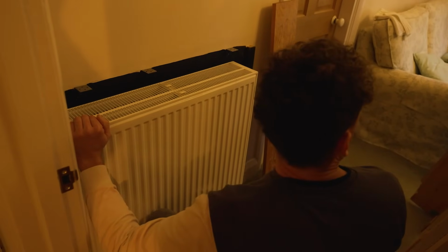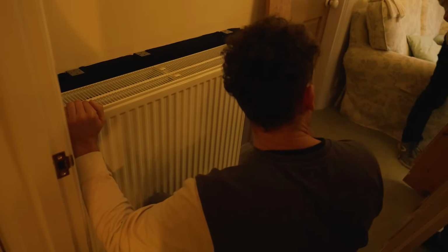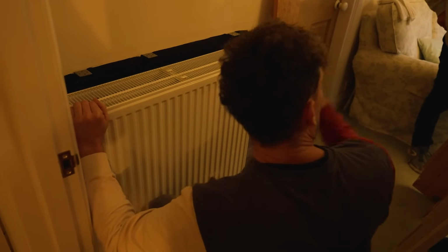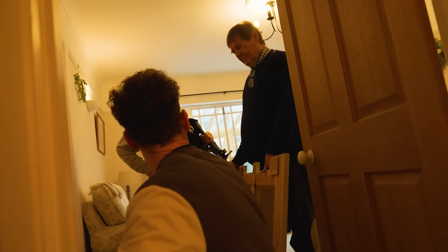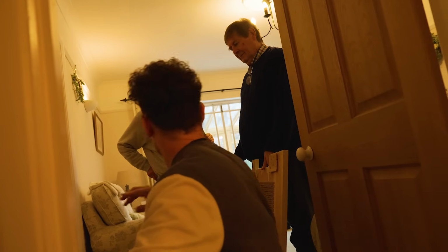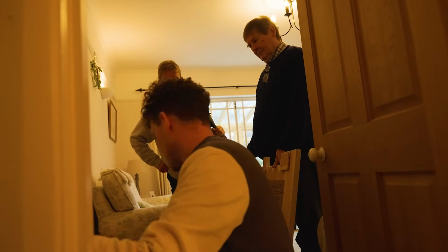And is anything that can be done about it? Yeah, we just need to make sure your pump is turned up and balance down any overflowing radiators. So if your temperature difference is too narrow elsewhere, we turn down those radiators, which force more flow to this radiator. So the reason this room feels cooler is, one, because of this, but this is a much bigger impact.